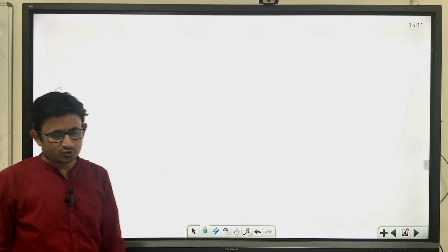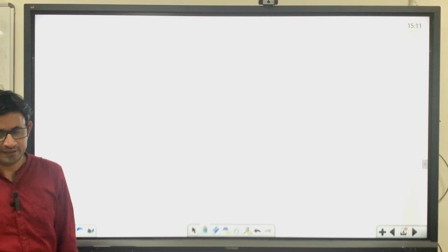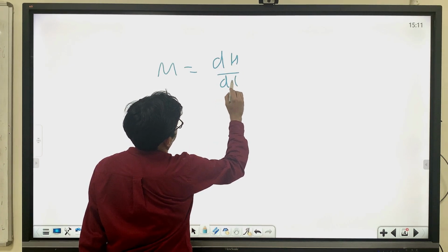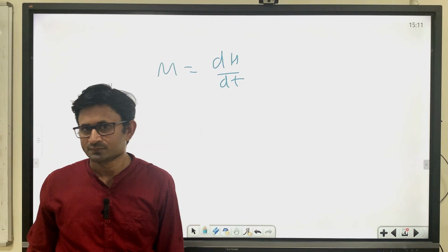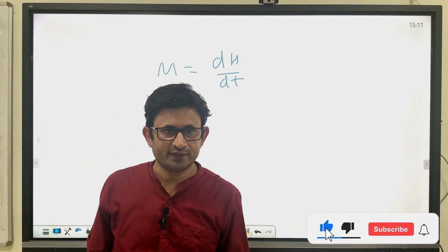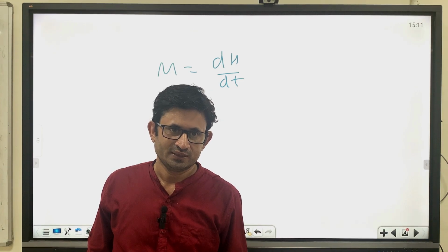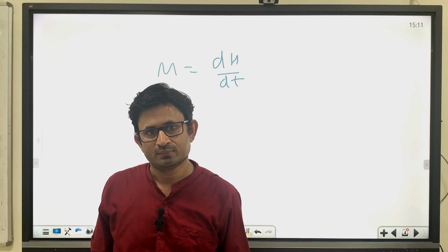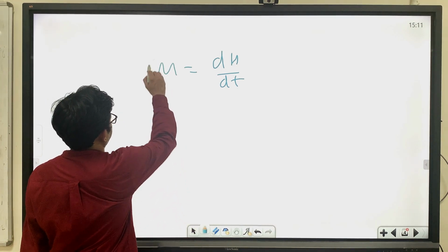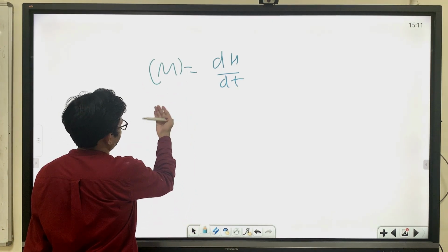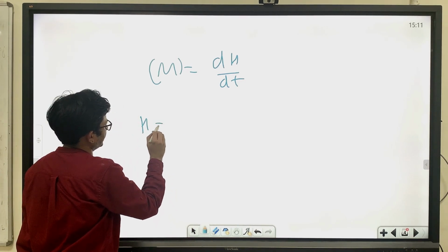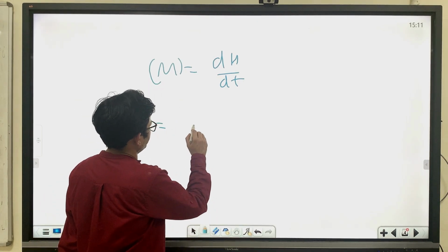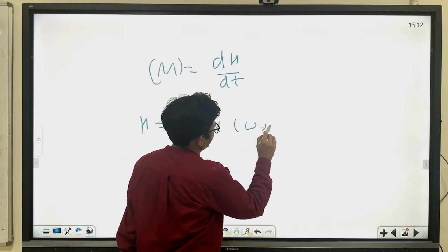Okay. So you might have studied that the moment is the rate of change of angular momentum. The force is the rate of change of linear momentum, and the moment is the rate of change of angular momentum. And now here my interest is what? Find out the moment. So this will have a roll, pitch and yaw moment. So first we have to find out the angular momentum, right? So what is angular momentum? Angular momentum generally you write r cross omega cross r, right?